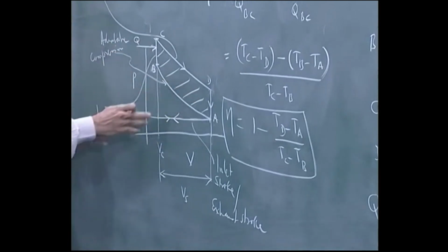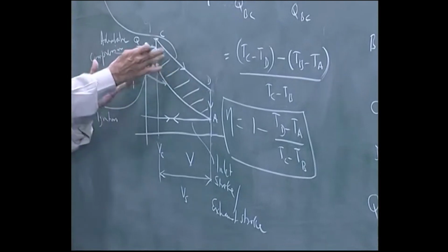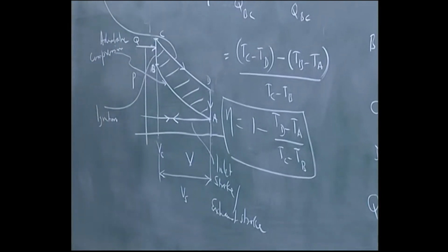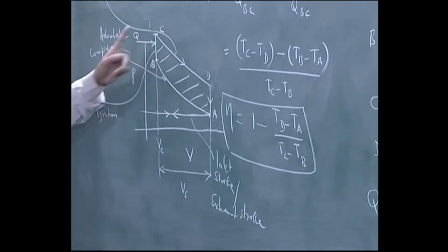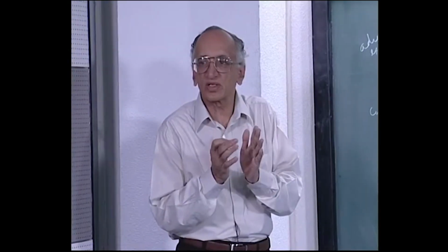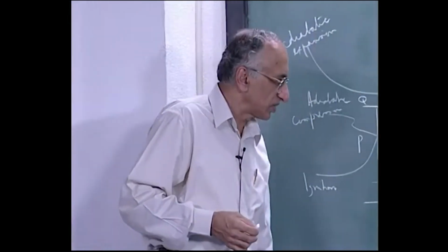So when you expand it out, this gas remains, when you finally expand it out, that gas remains in the system, and so it occupies space much more. At atmospheric pressure it occupies more space than it would before. So essentially it represents a loss, because you have the spent fuel air mixture that is still occupying the space inside the cylinder. So clearance volume represents loss.